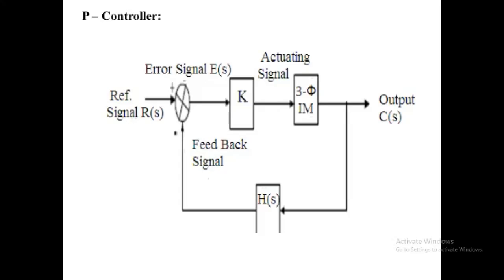The error signal is given as e(t) = K[r(t) - h(t)], and it is desirable that the control system be underdamped from the point of view of quick response. An underdamped control system exhibits exponentially decaying oscillations in the output time response during the transient period.